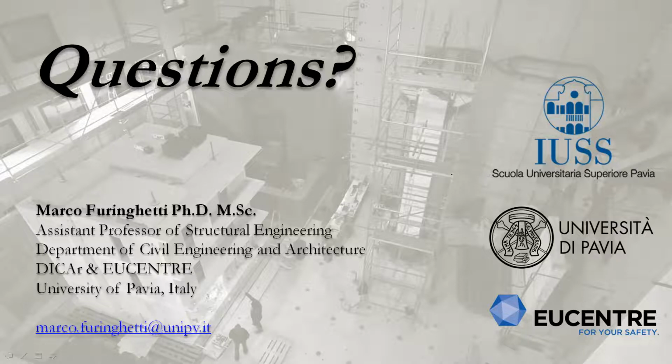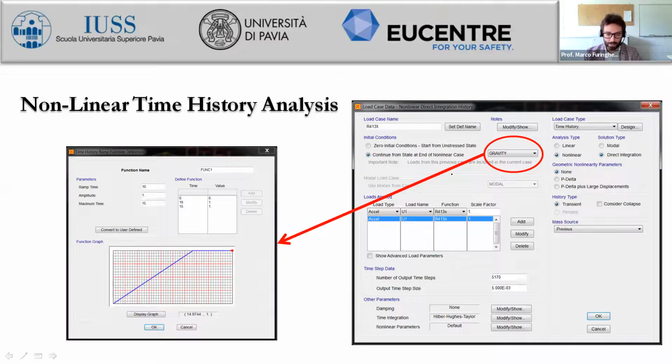Thank you. Okay, so depending on the damping assumptions, we have different hypotheses that can be applied to our models. There could be mass proportional, stiffness proportional, or Rayleigh damping generally for both of them, so both stiffness and mass proportional. We have to keep in mind that we are actually modeling an isolated structure.